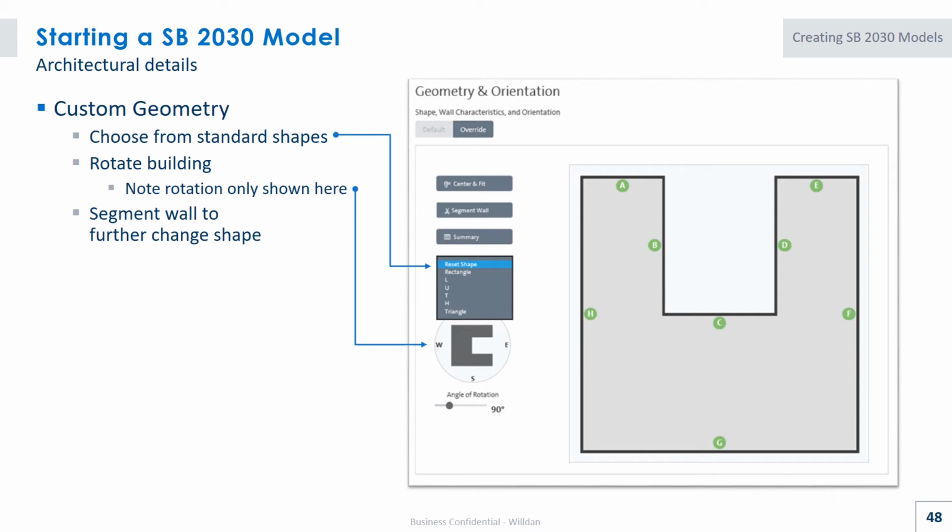So if you're building like a traditional downtown where it's just a series of buildings, one right next to each other, and the walls are shared walls, you could have the outside walls, the side walls of your building be adiabatic. Or if you have multiple space asset types that are touching each other, they can be adiabatic. And it can either be the entire wall, or it can be a certain width and height of the wall that's adiabatic. Again, this is trying to get close to the right amount of wall area, although you don't have to get it to be dead on accurate.